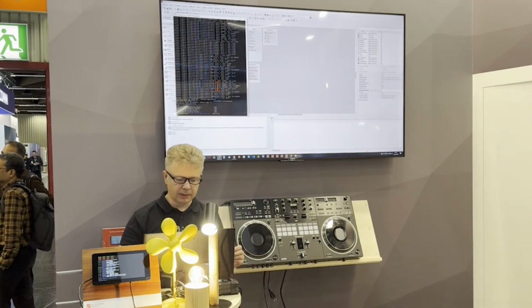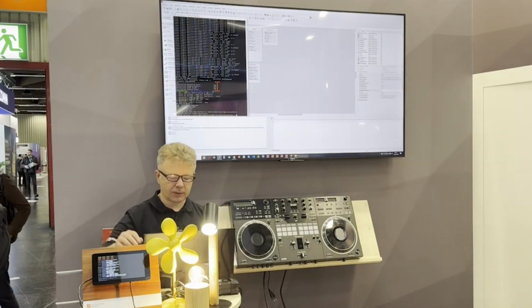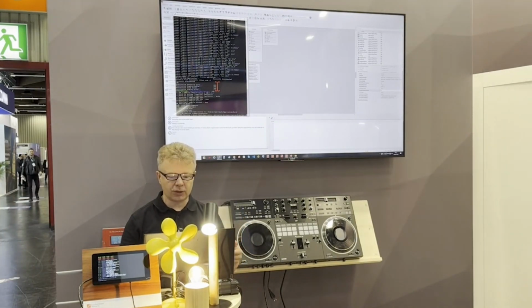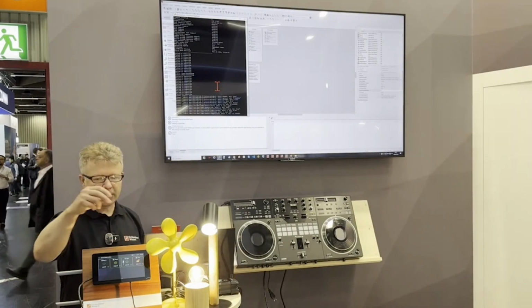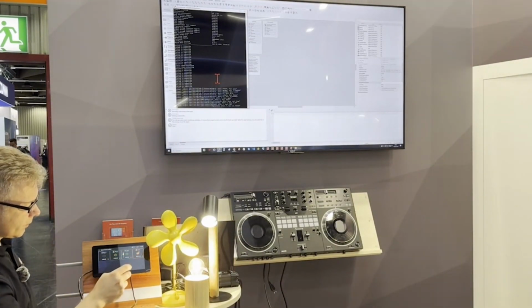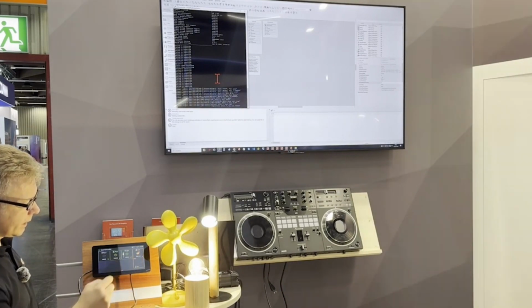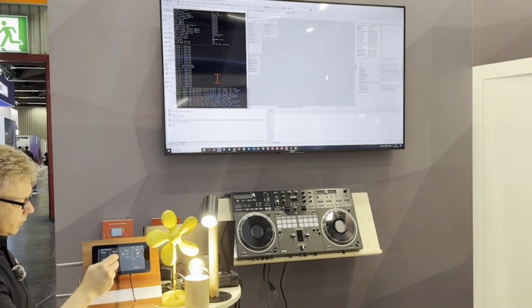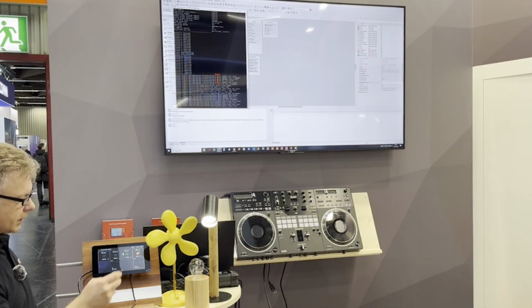It's done now. I start the build process. It's compiling directly here on the Raspberry Pi, all the stuff which I just generated. And as soon as this is available, I also can check it here and just have a look. You also can see here that this lux sensor is now adjusting in a value range from 0 to 9,000. And that's what I want to see. And it's reacting in the same way as I did on the prototyper.